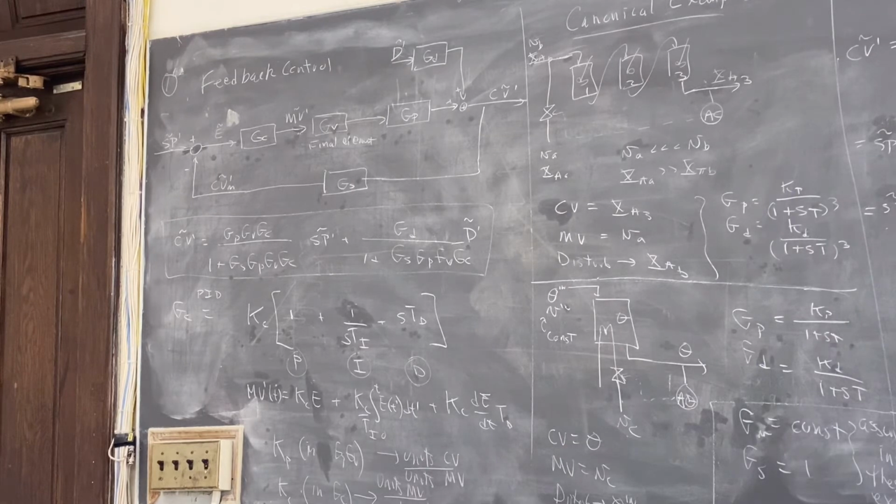Note that in electrical engineering problems, that's not necessarily the case. In electrical engineering problems, they're dealing with circuits where the process is something electronic, and the process can respond also in a millisecond. So there they have other issues. Control is more complicated for electrical engineers because the time scales for the process could be the same order of magnitude as the time scale of the computation, or even faster. So they have much more serious issues. That's generally not an issue for chemical engineering processes.